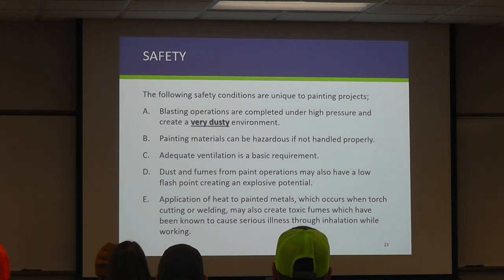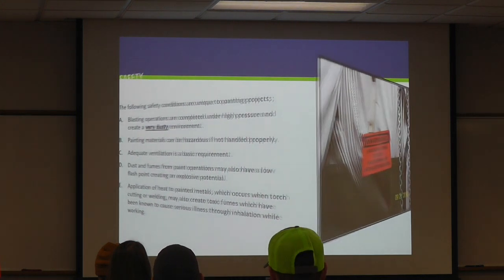One big thing, if they end up having to heat any painted metals, any torch cutting, welding, any repairs that have to go on prior to doing any coating or additional blasting, make sure that, well, one big one is if you're cutting on anything galvanized. I don't know if anyone's ever put a cutting torch to galvanized coatings before. It's a smell and taste you'll never forget. It's pretty nasty. It's not good for you. So again, please be sure you have the proper PPE.